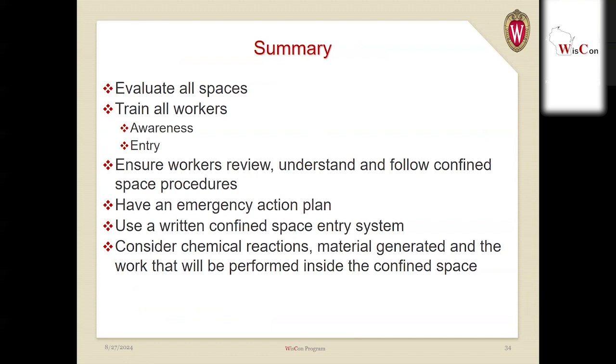You also have to have an emergency action plan. You've got to have it written down, and people need to understand what happens if an emergency occurs. You need to have that written confined space entry system. And also, when you're doing work inside the confined space, you really need to consider what's going on. Are there chemical reactions with what's happening in the space? Are you generating some type of hazardous atmosphere because you're in there? And what other work is going to be performed inside that confined space if there's more than one crew working in it?